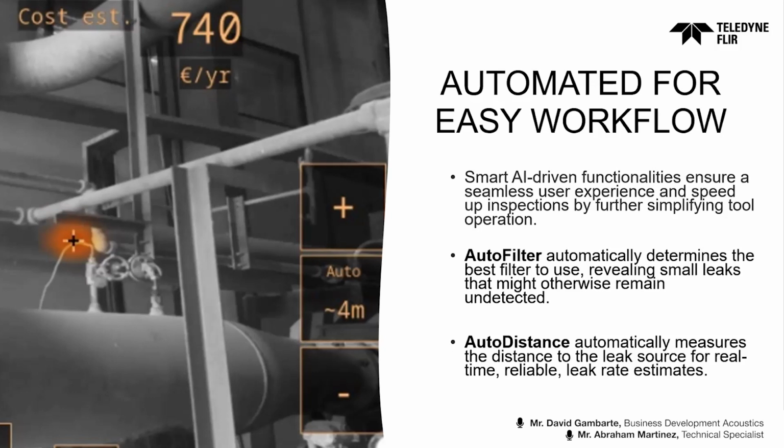And the auto distance, as I mentioned, makes quite a difference in the life of users, because up to 5 meters, which is a very normal distance for leak detection in many industries, they can just scan with the camera and find the leaks without any need for distance estimation and so on.